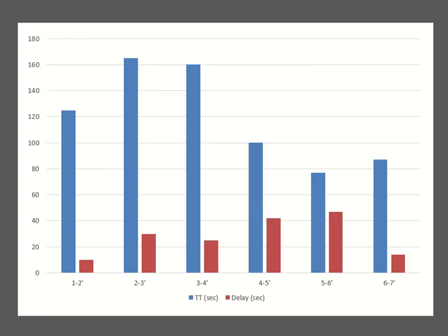Okay, this is the graph plotted for the delay. Delay was given and the travel time we calculated, and for drawing the graph, the entire travel time is converted to seconds. So if it was 2 minutes 45 seconds, they converted 2 minutes to seconds plus 45, and so on and so forth. So you can see here the section with the highest travel time is section 2 to 3. Okay, but the section with the highest delay is 5 to 6.